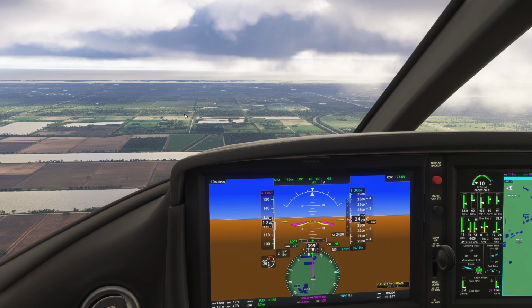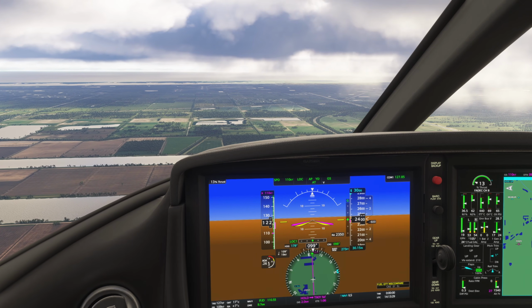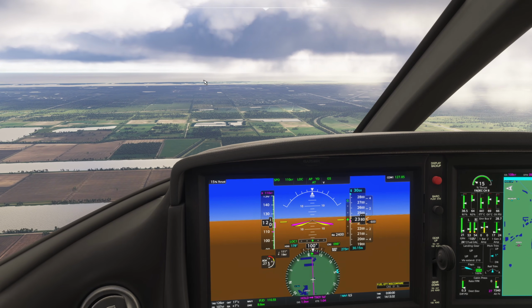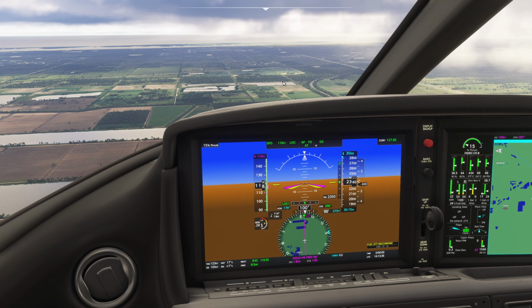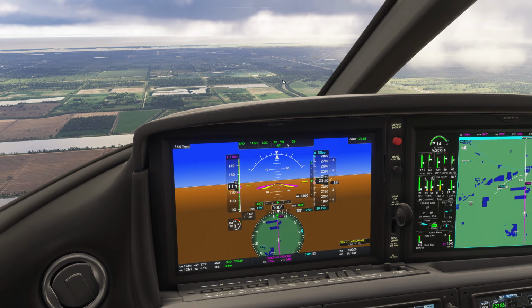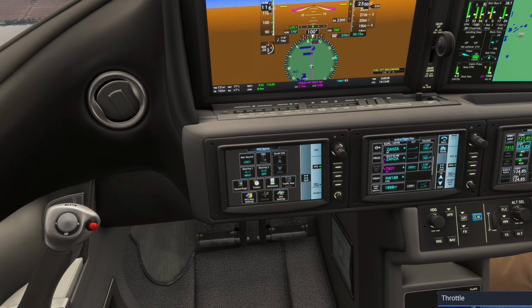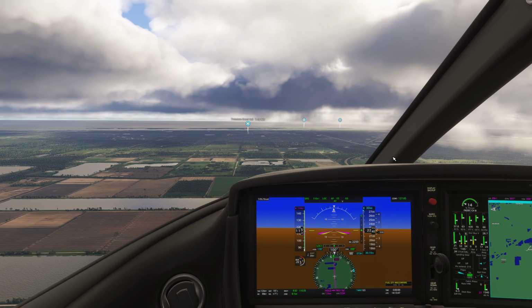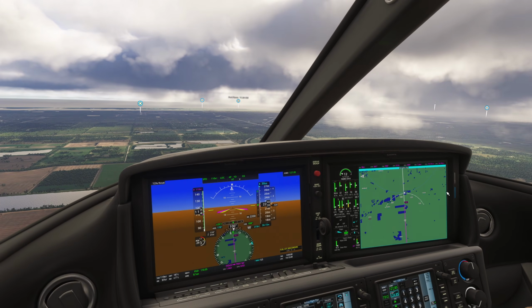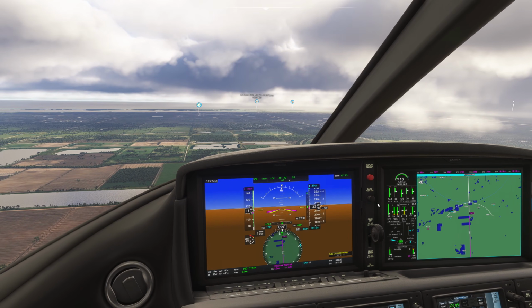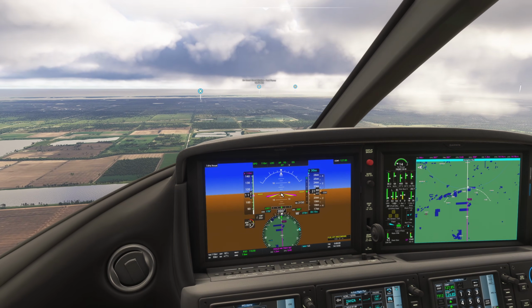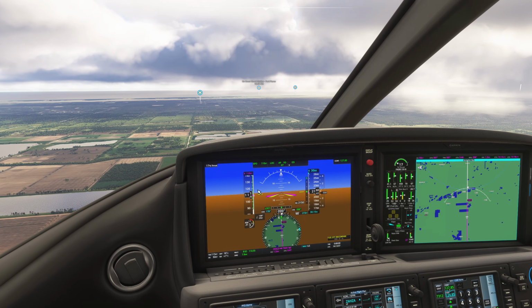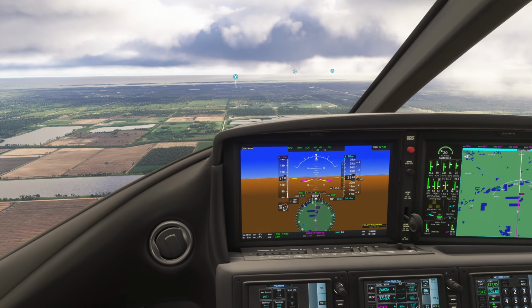Then we're going to get ready to make sure we're at 90 as we go over the runway threshold. Well, before we get to the runway threshold, we should be targeting 90, but we're going to manually do that with our thrust lever. So gear down. At Tiki, we can put the gear down. Now, so slowing down. Plane's going to hold 110 knots.